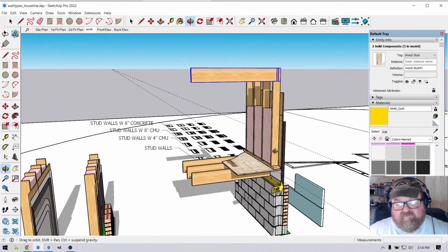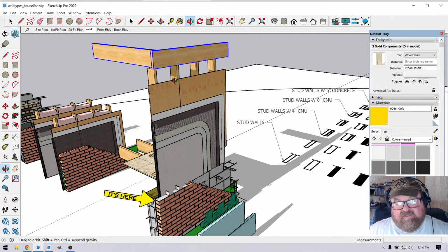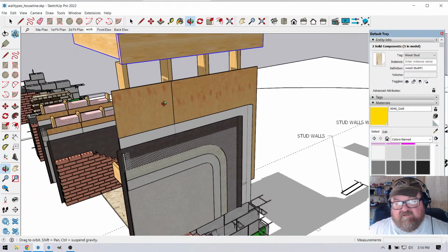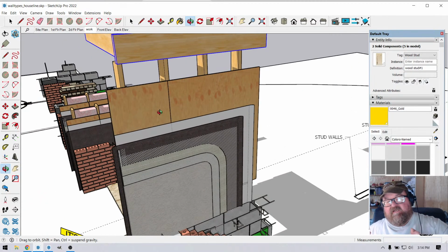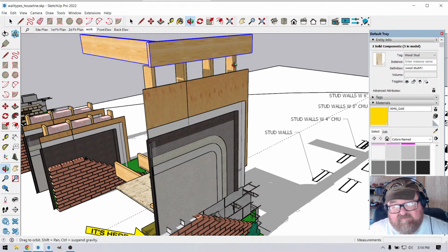A lot of people get by with laying the OSB down on its edge, but only because typically in a house you will have interior walls that brace the house. I think the rule is you can't go more than 30 feet of unbraced wall. If you do, it's a shear wall, and that's where these requirements kick in for nailing patterns on the OSB. So that's how they get by sometimes with laying it down.